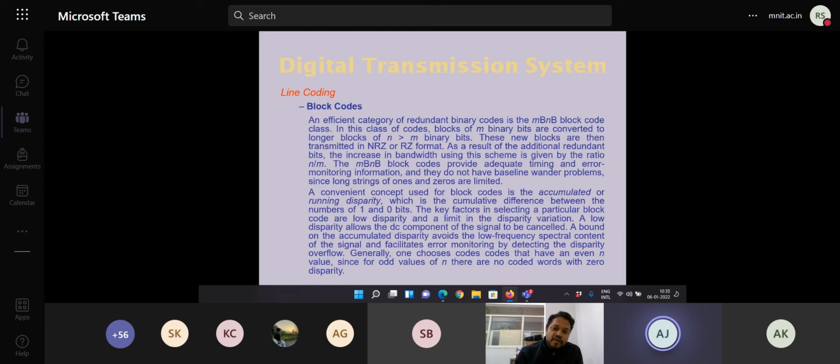Any practical communication system includes forward error correction, and depending on what the channel is, there can be different types of forward error correcting systems which can be employed. Block codes are only one type of code which does error correction, but there are also convolutional codes.